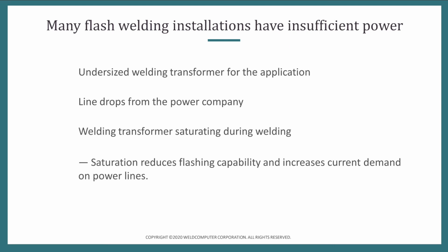Now, many of these flash welding installations have insufficient power to generate a consistent flash, because you're running wide open on your voltage, or you have a system where you're using taps. We run into installations where line drops from the power company mess them up, and they can't function during certain time windows.